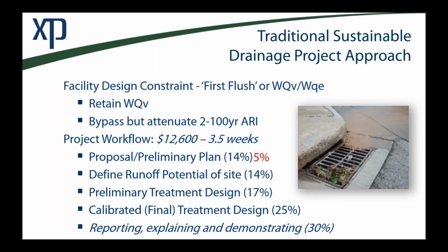Now, what I'll start showing here is, I think, in the real world, how we might actually spend time on this. I'd say maybe a little bit less than a day is our preliminary plan, a back of a napkin proposal. Then it doesn't take very long to delineate our runoff potential on the site, even laying out the treatment, our initial guess, maybe our overly optimistic guess of how we can get away with treatment. But the vast majority of time, we're going to spend calibrating.